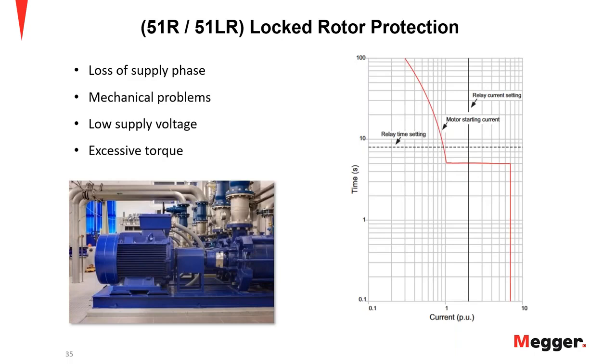The locked rotor protection is basically protected with an overcurrent relay with an adjustable time delay. And this relay will trip the motor when it exceeds its permissible starting time, but before the safe stall withstand time.